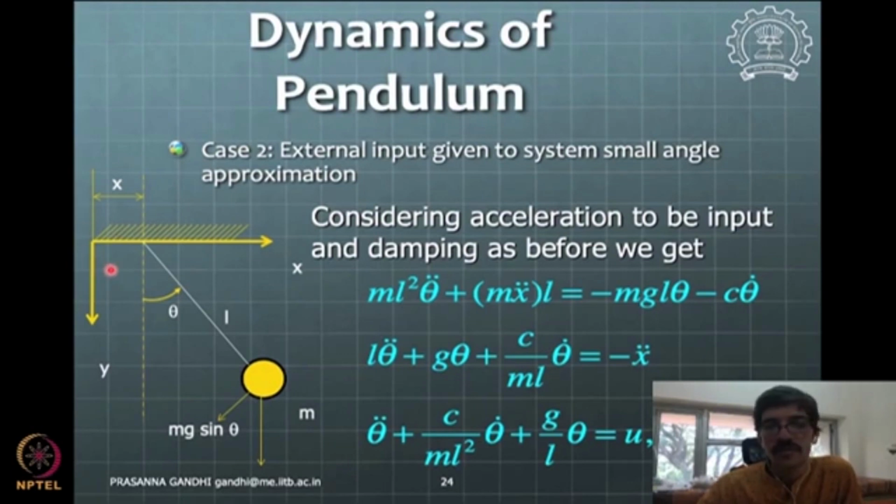Okay, that much I can tell you as a physics part, but to really get to this, you will need to write the equations in the form of this pendulum cart total system. So that will be a 2 degree of freedom system, the cart degree of freedom and the pendulum degree of freedom theta, and the force considered as an input. So a single input but 2 output kind of a system will be there.